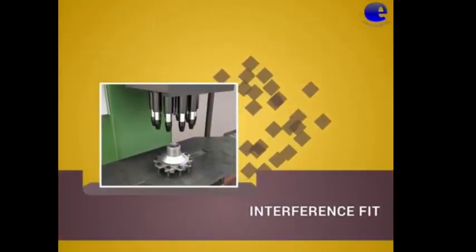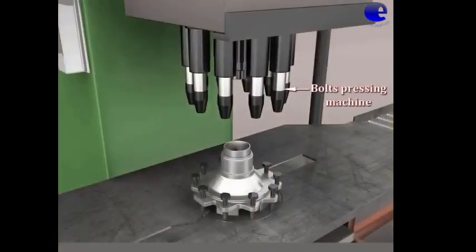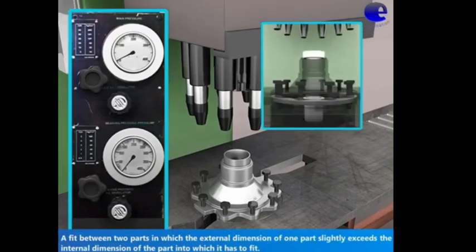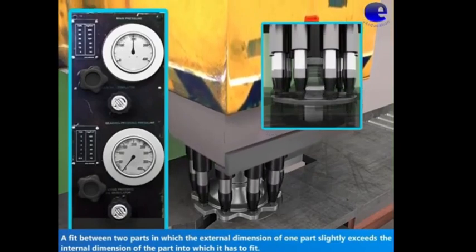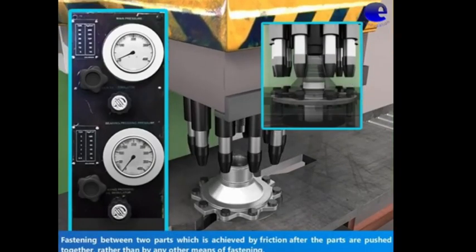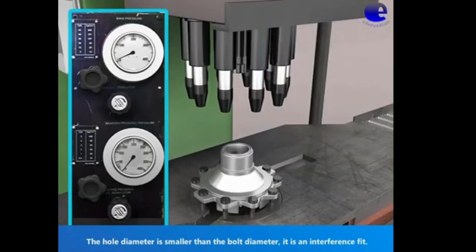Interference fit. In this video, we are going to see about interference fit. Consider a bolt pressing machine, hub, pressure gauge. A fit between two parts in which the external dimension of one part slightly exceeds the internal dimension of the part into which it has to fit. Fastening between two parts is achieved by friction after the parts are pushed together, rather than by any other means of fastening. The hole diameter is smaller than the bolt diameter. It is an interference fit.